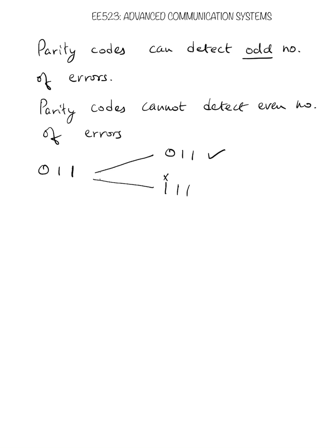The number of ones here is 3, which is odd, and therefore the receiver would say there is a problem with this code word and detect the error. It detects the error, no problem. And suppose we introduce 2 errors in this. Let's say the first bit 0 became 1, the second bit, which is 1, became 0, and the third bit is correct.